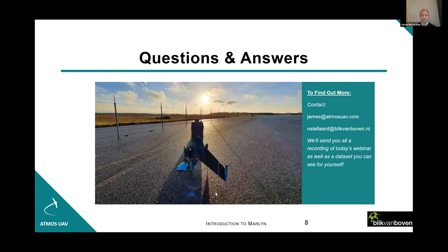Justin Huntley asks, is the system compatible with Trimble equipment? I think that's similarly answered in the last question. I believe Trimble doesn't, as standard, output Rinex data. I'm not sure if you know anything about that, Norbert, but I think we've had some situations in the past where some customers have used it, but I think Trimble has a free to download software which is going to allow you to convert your data from the base station into Rinex, and then it's fine. You just have that extra conversion step.